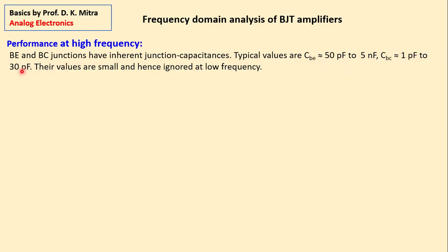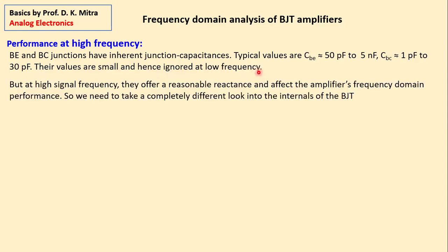That means they are very, very small capacitances. That is why in audio frequency analysis, we totally ignored them. We didn't talk about them at all. But if your operating signal frequency is very high, their values are so small that they are ignored at low frequency, but at high signal frequency they offer a reasonable reactance and affect the amplifier's frequency domain performance.